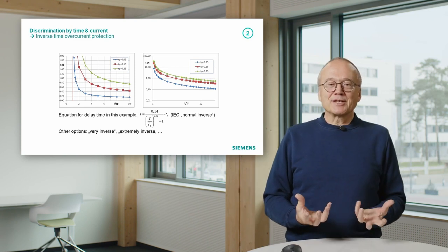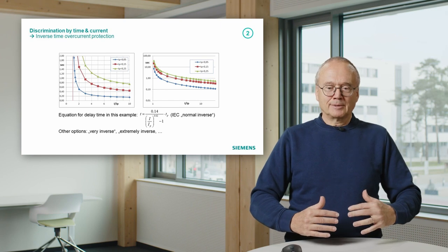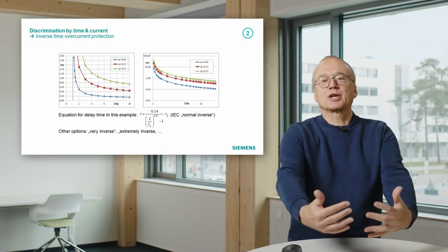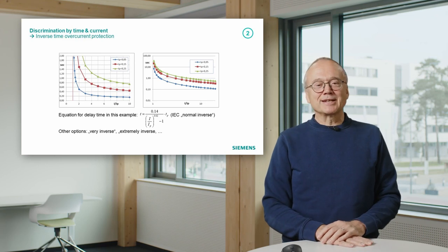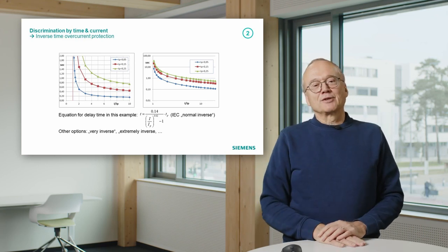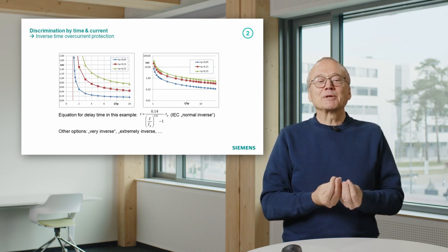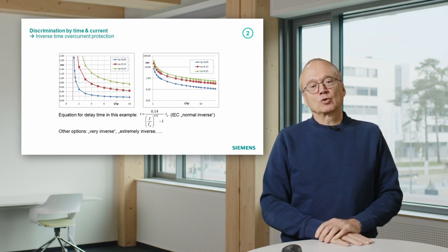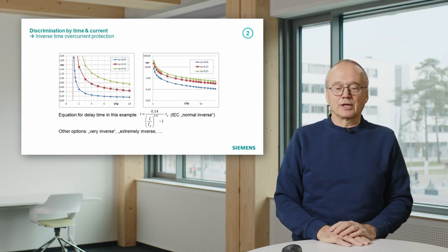But of course, this IEC standard had somehow to show what was already there before. That means what came from these electromechanical relays. That means what people in this committee did is they measured the curves from the electromechanical relays which were in operation, and then they did a curve fitting. That means they defined equations which lead to a curve which are pretty much similar to these electromechanical curves, and that is why we end up in such strange equations.